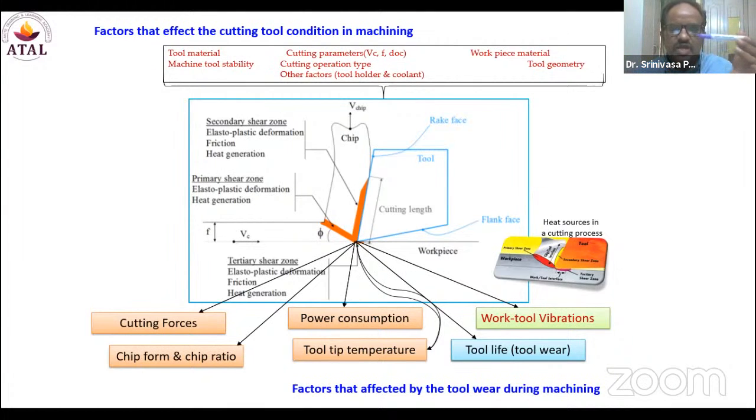When there is no interaction with the workpiece, in the case of 2-axis machining, that is lathe operation, boring operation, and in the case of 3-axis machining, drilling, milling, the spindle is going to yield almost negligible deflections. This spindle in 2-axis is going to yield very little deflection. They are not going to affect the stability or condition of the machine.